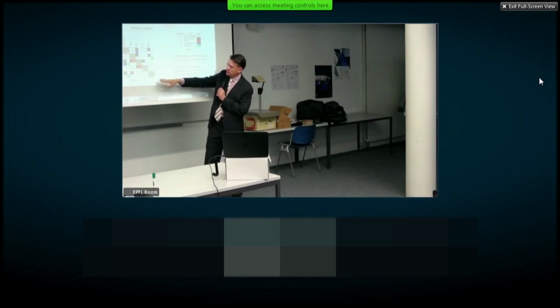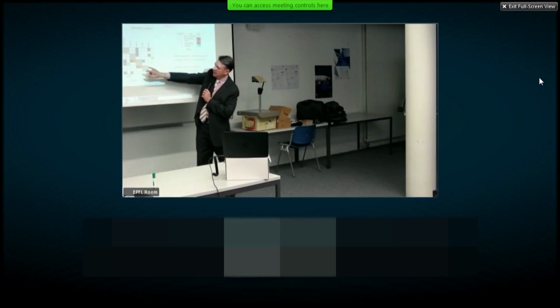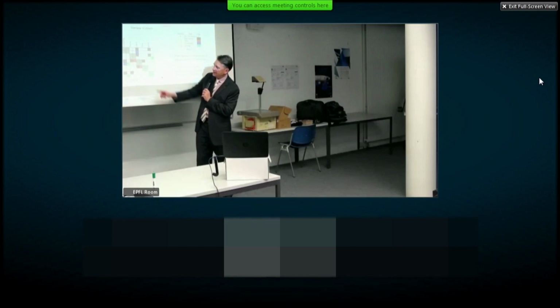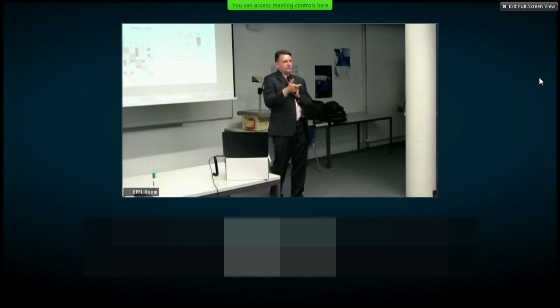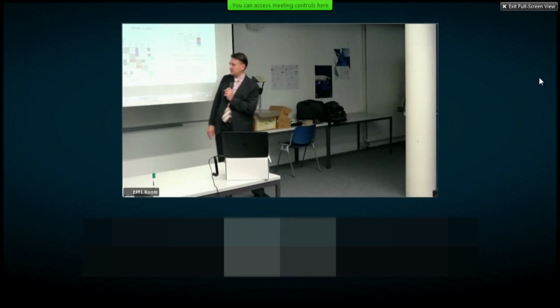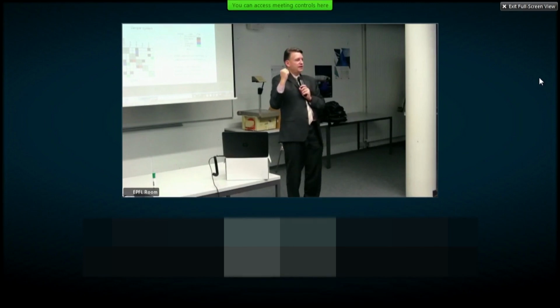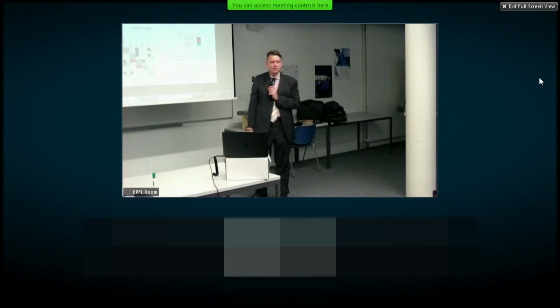A DSM is always a square matrix where your components are the rows and columns, equally labeled. On the diagonal there's no information, since a component connects with itself, so you keep the diagonal blank. All of those interfaces and flows we mentioned are shown as off-diagonals. You have to be a little careful because there are 2 definitions of DSM, depending on the inflows and outflows. The definition we mainly use in North America is where the inflows into a component are horizontal. So the controller sends information to the valve. This is that blue square right there, and you can see that shown here on the block diagram. But the valve also sends information back to the controller, probably that the valve should open or close, and when the valve is actually open, it would confirm back to the controller the status of the valve as open or closed.